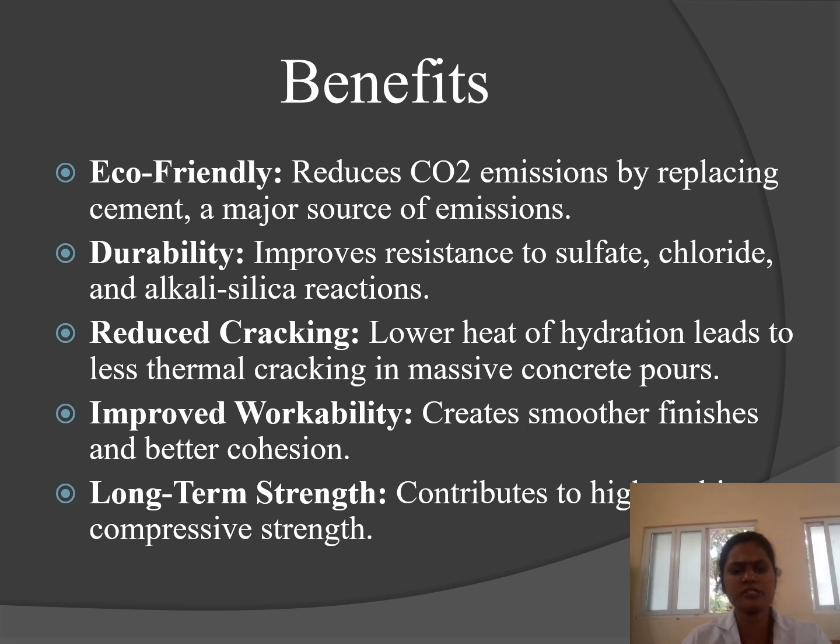So what are the benefits of GGBS? Eco-friendly: it reduces CO2 emissions by replacing cement. Next is durability: improved resistance to sulfate, chloride and alkali silica reaction, reducing cracks. Lower heat of hydration gives less thermal cracking in massive concrete pours. Improved workability creates a smoother finish and better cohesion. Long term strength: contributes to higher compressive strength.